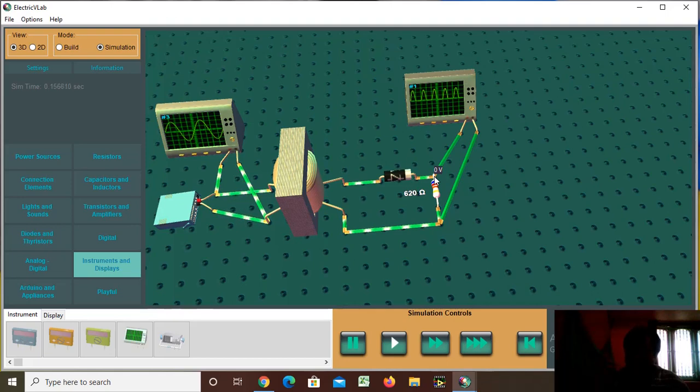When it falls below 12 volts, the negative half cycle has actually started. Yeah, you can see again it's rising during the positive half cycle. Around the maximum voltage is 11.3, and again it will become zero. Again you can check the positive half cycle, it will give some voltage. Now the positive half cycle has started.